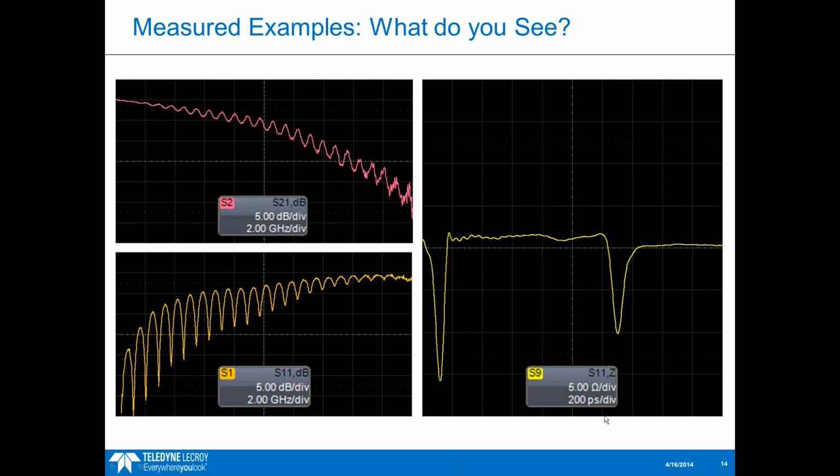When we look at the impedance plot, we can see about a 15 ohm impedance variation at each end of this microstrip line. These are the SMA connectors that we're actually hooking up our test port cables to, and these are very capacitive and are causing a lot of reflections. So this was actually a 50 ohm 4-inch microstrip line with some pretty capacitive launches here.